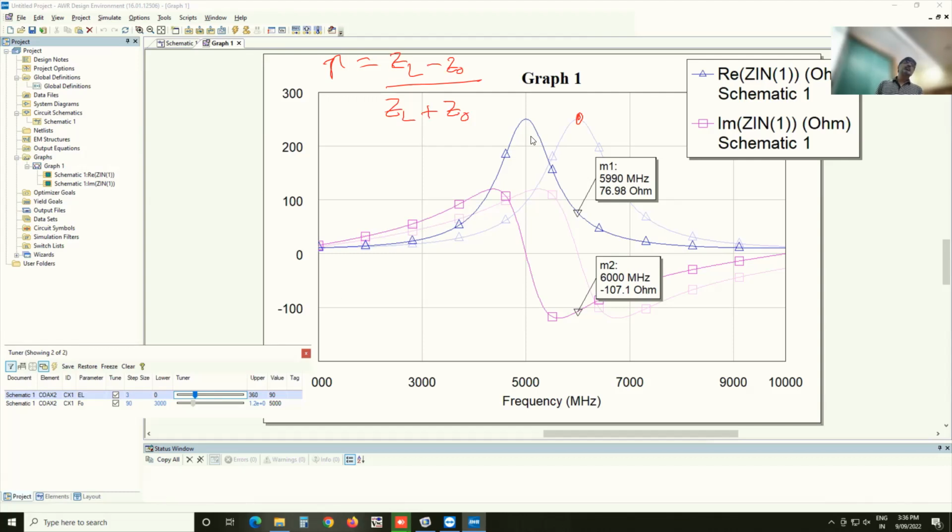Like at 75 degrees and 5 gigahertz, the imaginary part is also 0. So that's a constant. Like 90 degrees at 6 gigahertz, there we're also getting an imaginary part of 0. But at different frequencies. So if you want to do impedance matching at 6 gigahertz, you will design it to have 90 degrees at 6 gigahertz. So we are fixing this because of 6 gigahertz. That's right.